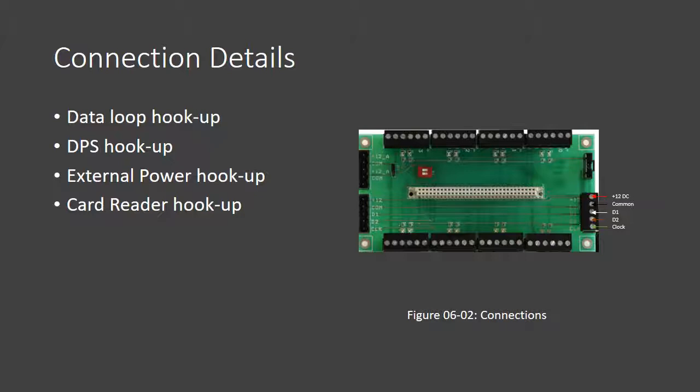If you're going to connect a dry contact input or DPS input for this board, you'll need to make sure that you're using the 81651 decoder board in the I/O card slot on the board. That will provide the functionality for receiving those inputs. And a DPS or a dry contact input connects in the following way.